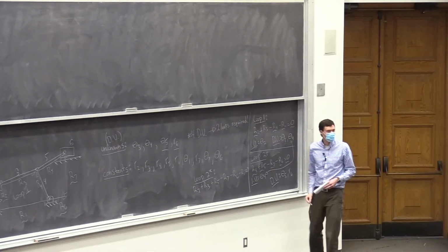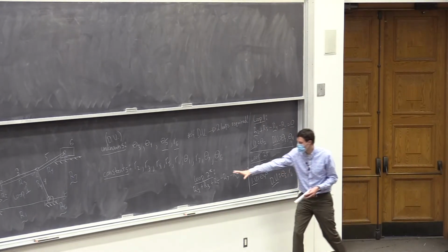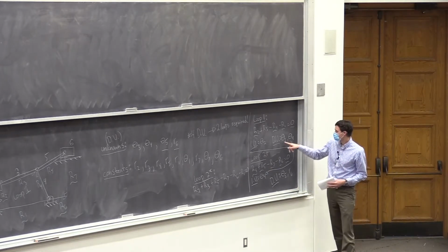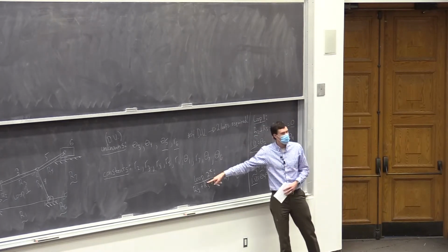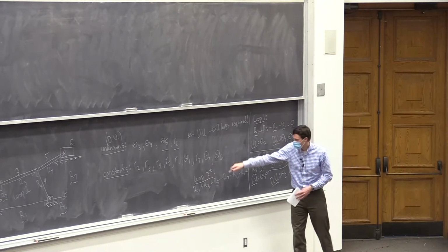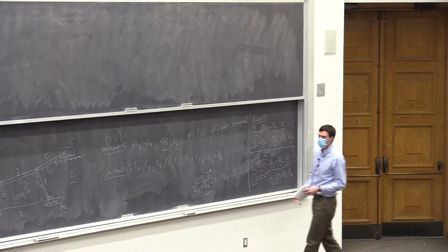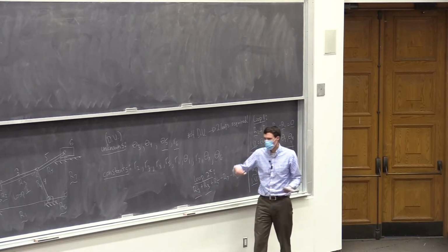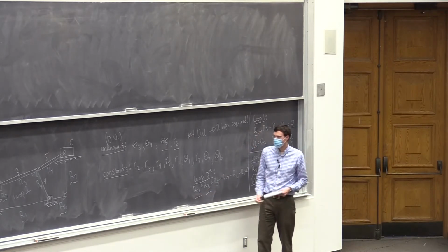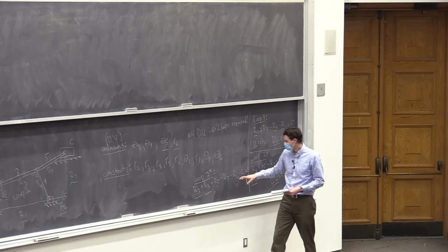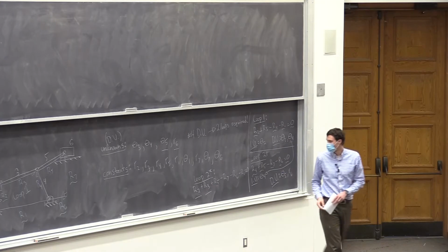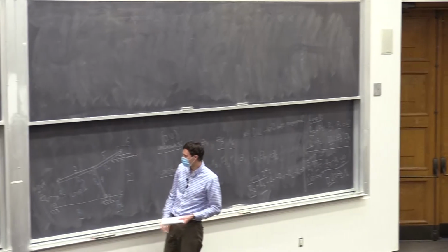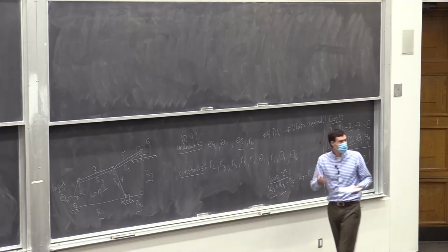It has more variables, so I would be attracted to loop 2 rather than 2 star for simplicity. But you could do that as well. And in that case, theta 3 would get transferred from loop 1 to loop 2 star. So theta 3 would be like the independent variable for your second loop. And theta 2 would also, you'd also know that. So you could almost think about it like this has 2 inputs, theta 2 and theta 3. You could come up with another loop. You can think of whatever crazy loops you want that use these vectors. As long as there's 2 unknowns, you'll be able to solve it.